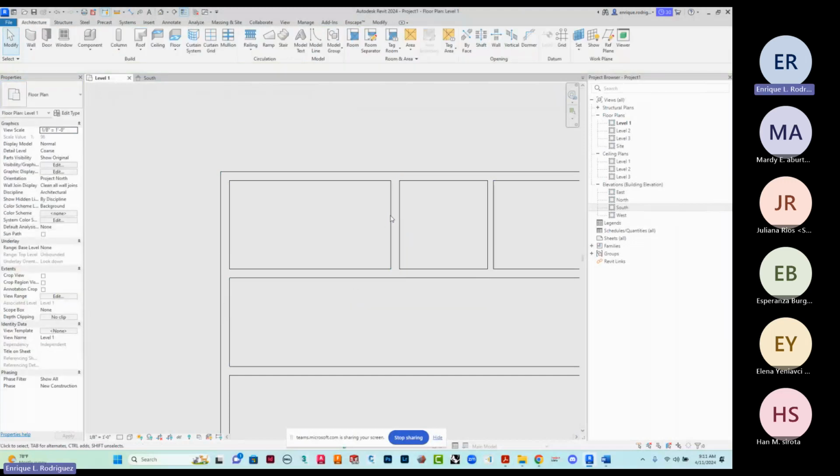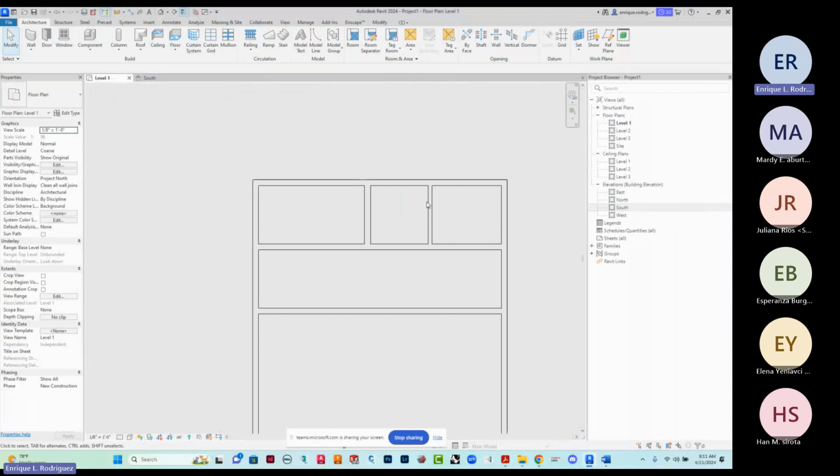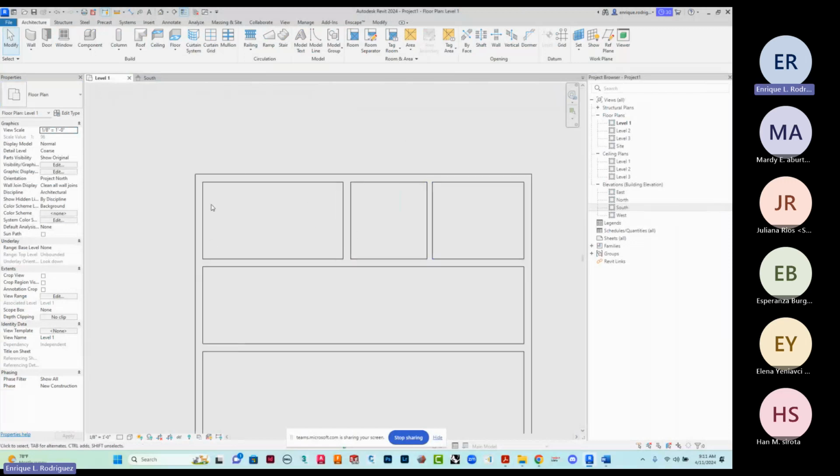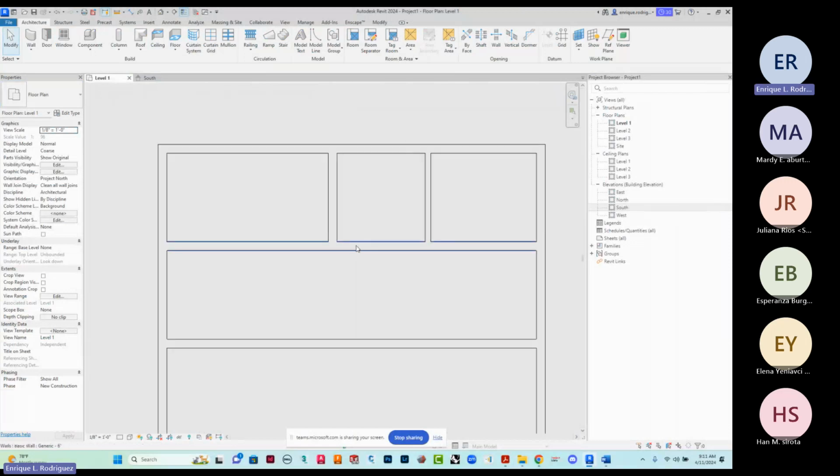And you notice it goes to the opposite side of where those dots were. That's the way it expanded. That's very similar to the justification line that you would have in AutoCAD Architecture when you were doing the wall. So now I can begin to edit this even more. This wall obviously is going to fill it this way, while this one is going to fill it this way. Everybody has a different way.